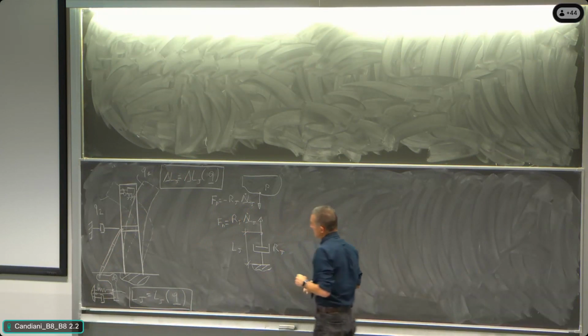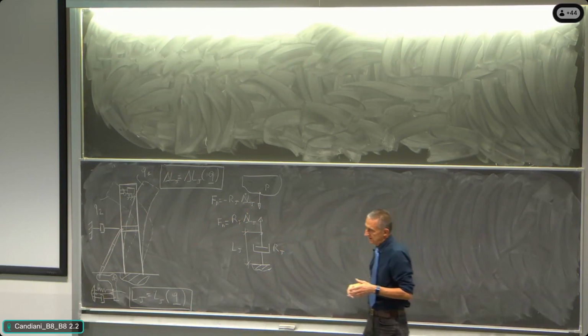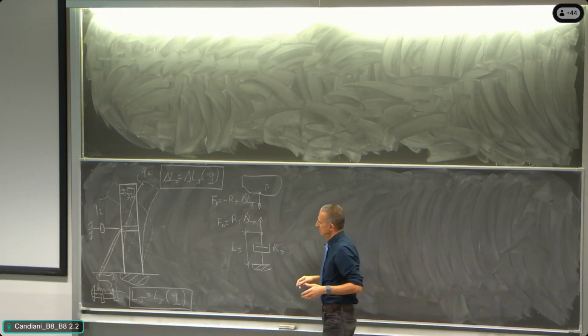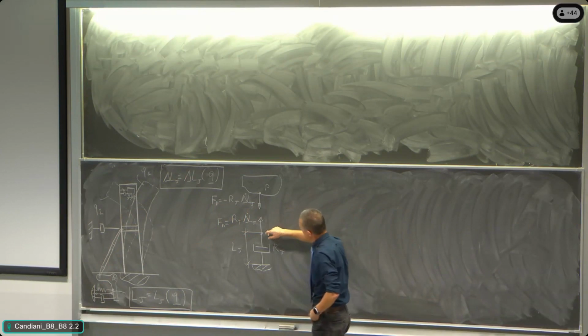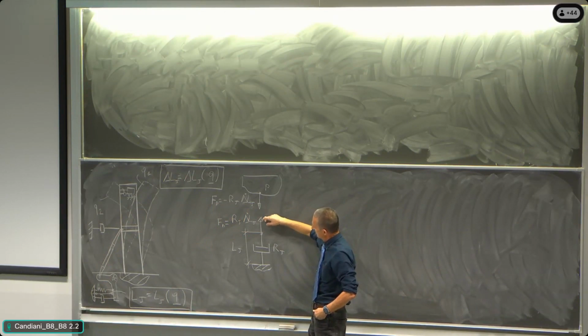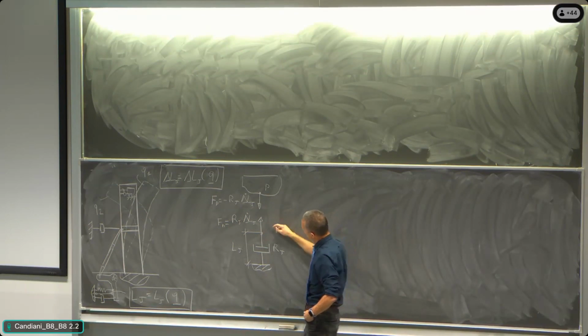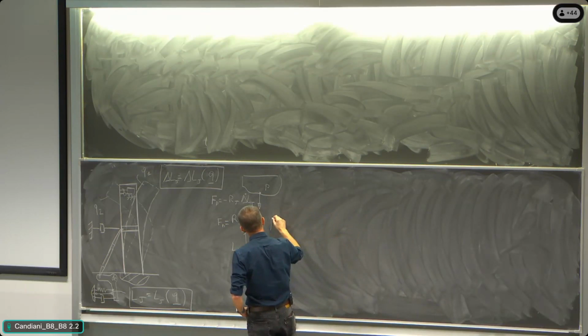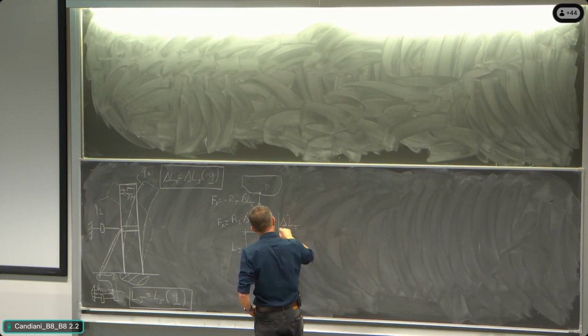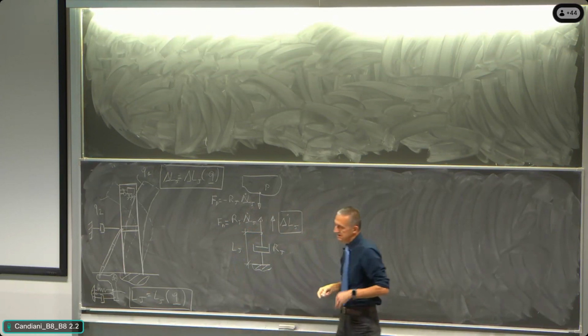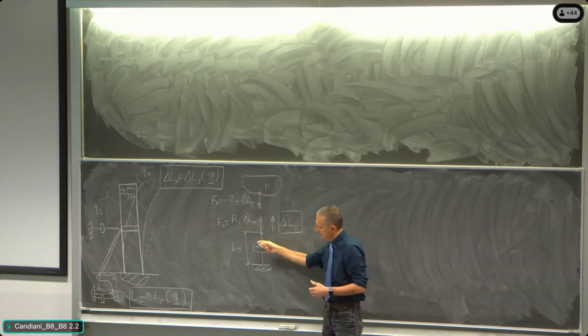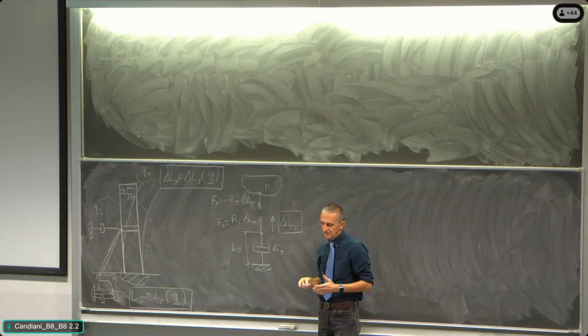In order to do this, first of all, we have to speak about the damper. I think that you should know what we mean about damper. A damper is a device that is responding with a force to a velocity. So the symbology, we are representing the damper in this way. If we are moving with a velocity that is shown here, and I repeat, delta L y dot. So delta L y dot is the time derivative of the variation of length of the damper, all right?